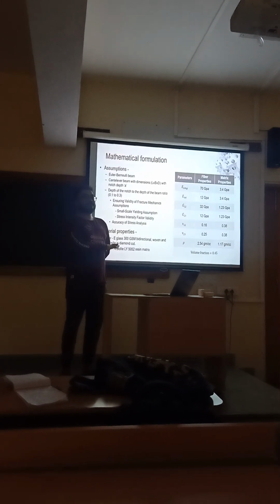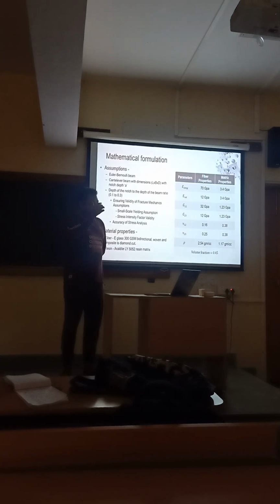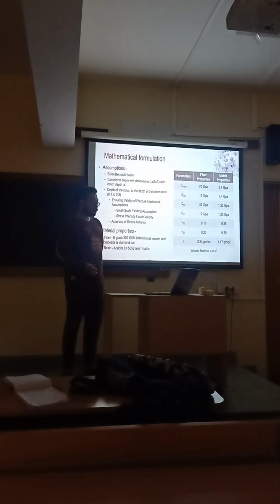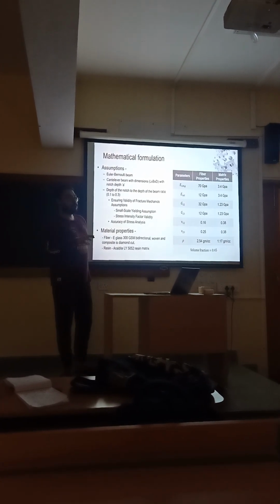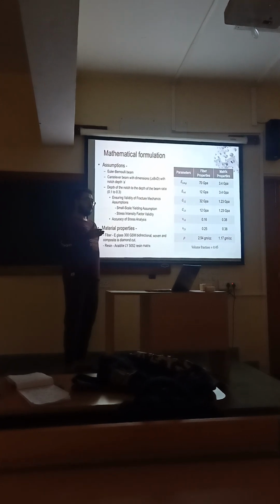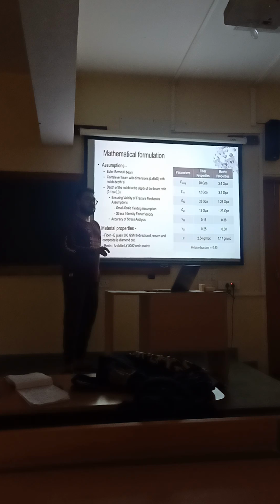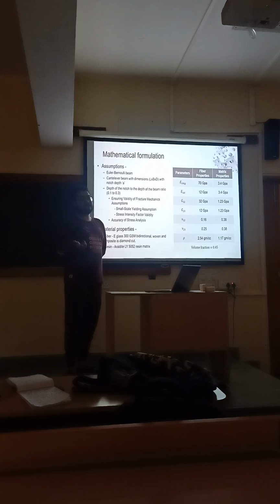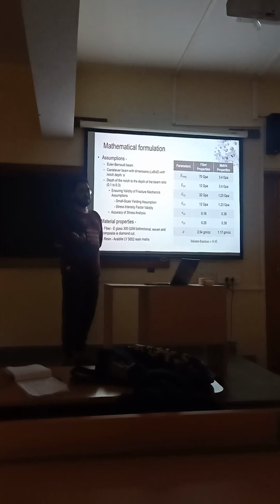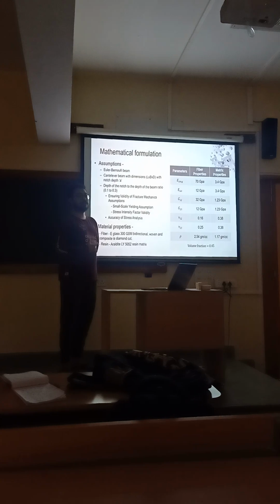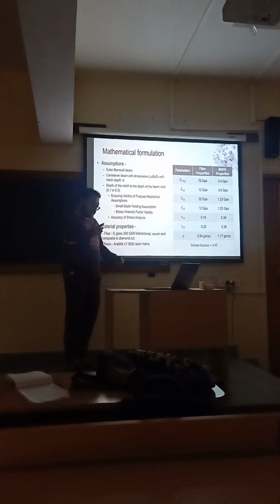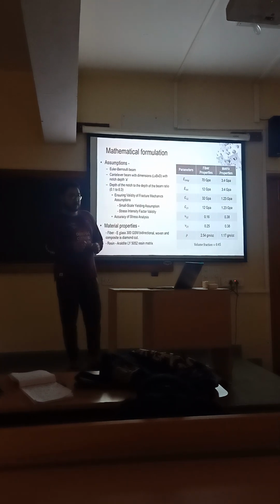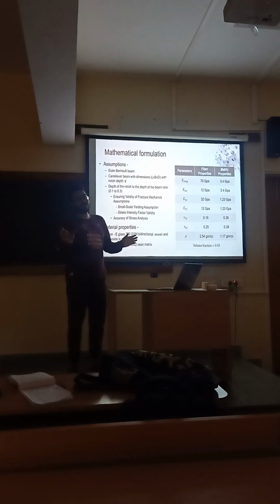I have used LEFM, linear elastic fracture mechanics. Linear elastic fracture mechanics has two main assumptions which are significant here. The first one is the small scale yielding assumption. If we go below 0.1 notch depth to beam depth ratio, it will produce an insignificant effect on the beam's mechanical behavior. It looks like the notch is almost non-existent. And simultaneously, if we go beyond 0.3, the beam will behave like two separate segments.